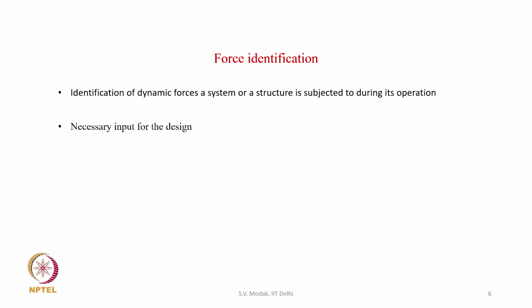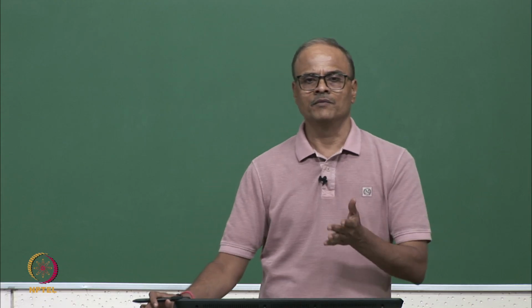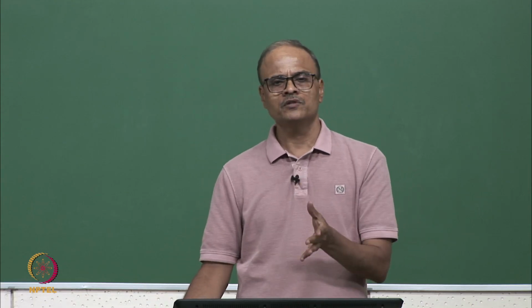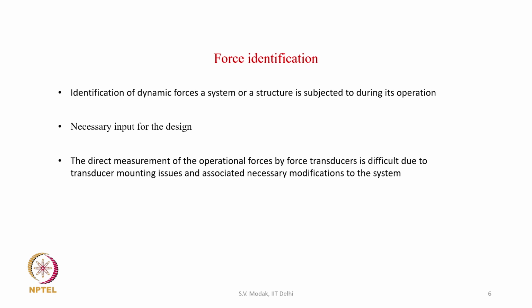One approach to know these forces is to measure them directly, by mounting force transducers. It is, however, seen that direct measurement of operational forces by force transducers is difficult due to transducer mounting issues and the associated modifications which need to be made to the system.